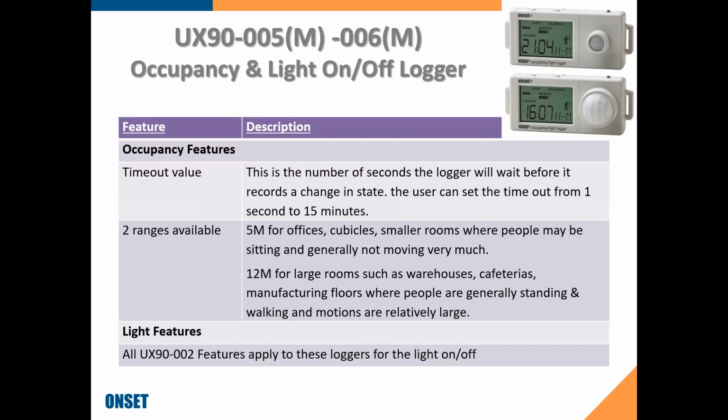And you're doing an energy study and you're trying to prove to your client that, hey, look, I think we can save you energy in these different conference rooms because I believe these lights are on all day and the conference rooms aren't being used. So you can set this data logger up, and you can log when the lights turn on, and you can also log when the rooms are occupied. So now you have a correlation of data showing lights on, room occupied, lights on, room unoccupied, and how long it happened for. So it's a great piece of data that you can go back and prove out to your customer that, hey, this is a good spot for control.